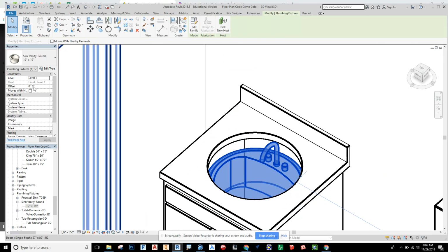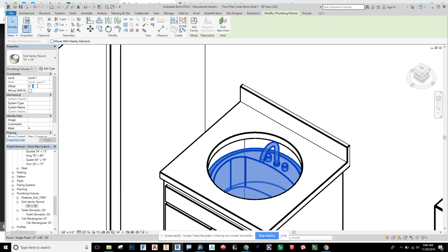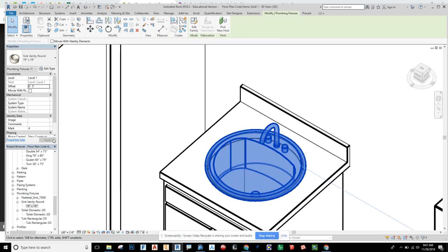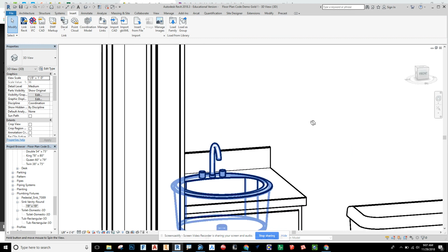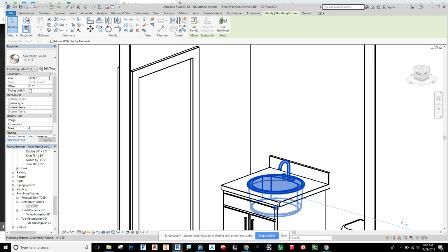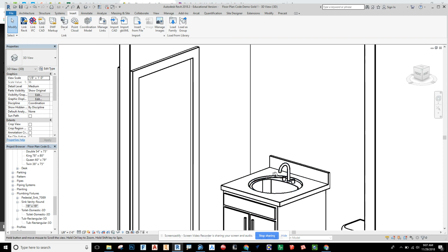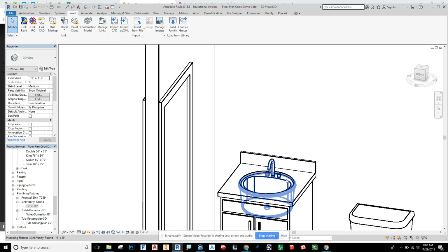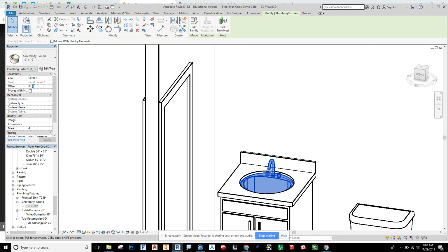I'm going to click on this sink, and it's a 5-inch offset with the customization that we made. Say apply. It looks like it's an overmount sink because of the lip on there. If it was undermount, we could just adjust it. If we want to give the impression of an undermount sink, which is a little bit nicer than an overmount, it wipes off the counter easier, we can just send that down by like an inch. So we're only going to offset it 4 inches. And now it gives the impression of an undermount sink. And actually, we might want to send that down, instead of 4 inches, maybe 3.5. Let's try that.